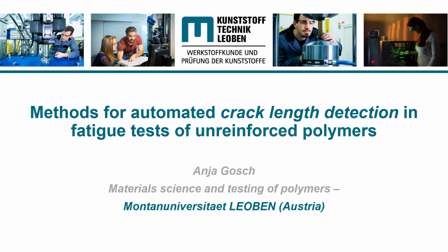So why is this topic so interesting? Because methods from the field of metals are not used in the case of polymers because it's not possible most of the time. And it's still state of the art to do the crack length detection during fatigue tests manually for polymers. This means by the use of a microscope. Therefore, the automation of this process is really interesting, which brings me to the introduction of my presentation.